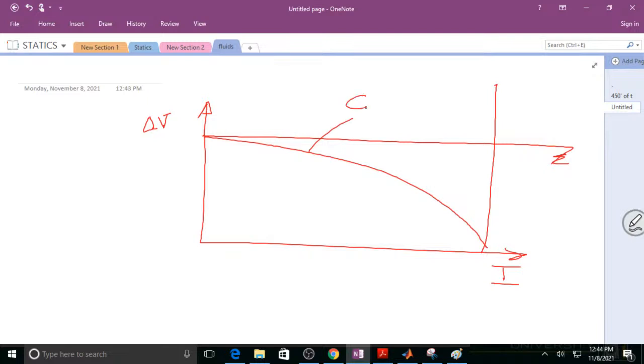As a matter of fact, this will be delta P, and that'll be the flow rate. Look at that. And so delta P is equal to some constant C1 minus C2 Q squared. That's what they usually model it as. It doesn't perfectly line up with the curve, but it's pretty close. And for engineers sizing pumps, it works pretty good. Close enough.